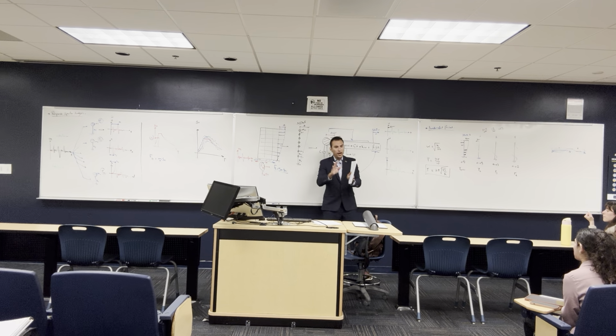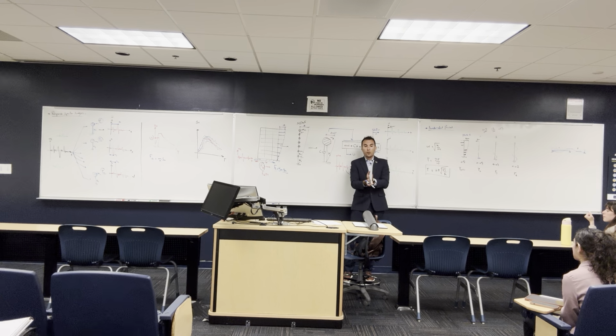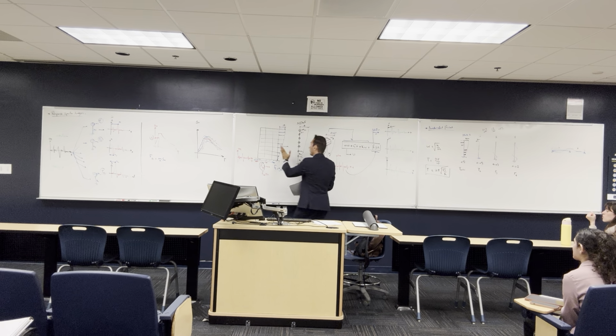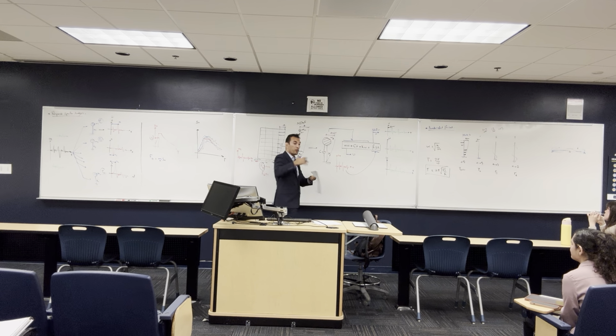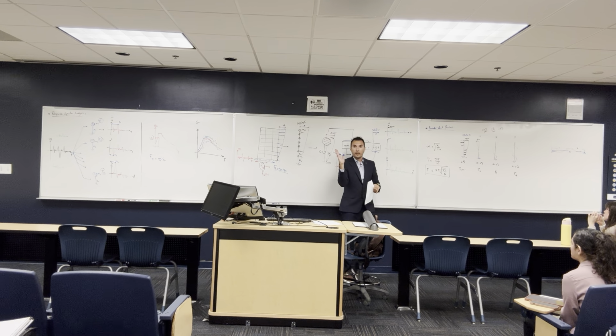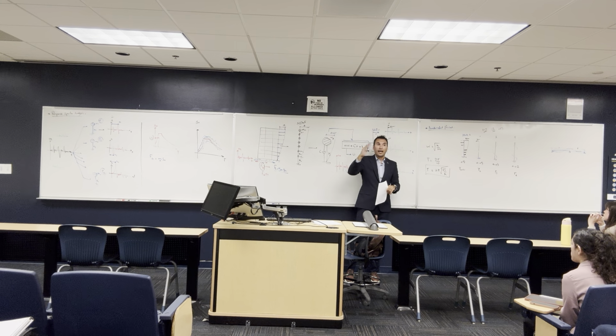All right. But if this building is going to be exposed to an earthquake, this column is going to have a bending moment that way, because you see all of them are moving like this. So you need to design this column to take the bending moment, but on the other side the column is going to have a bending moment too. So you will have to put reinforcement all the way around so you can resist the bending moment in X and the bending moment in Y, and also the axial load.